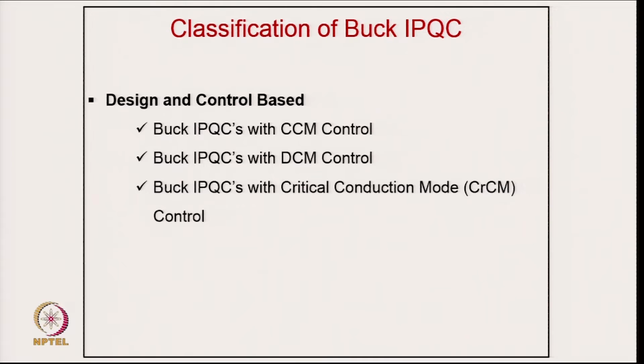Usually the continuous current or continuous voltage depends on the energy transfer component, like whether you are having energy transfer through an inductor. Then we call it continuous conduction mode, current mode of control. And if you are using capacitors as the energy transfer device in some of the converters, there you can call it continuous conduction mode of voltage across the energy transfer device. So, if you are designing CCM, of course control differs compared to the other one with buck